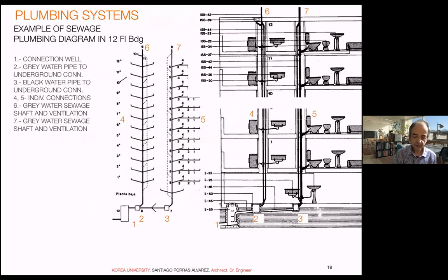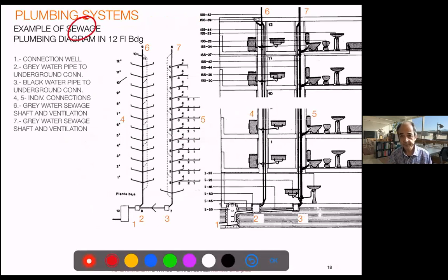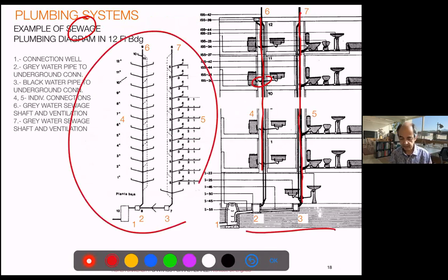And then we have the sewage, which usually is in parallel. And we usually will collect bathrooms, kitchens by separate. We need a shaft. And in this case, usually we share the sewage pipe. This is symbolic, again, at the same scale. Important, you need one connection, kind of small well that you can register in each of the connections. And we have a final also manhole, which makes the connection of the building sewage to the city. That is the connection element.